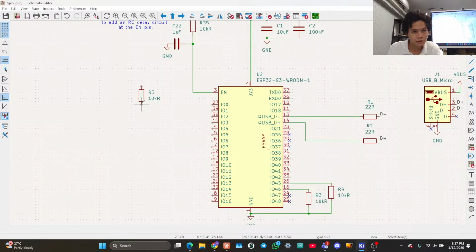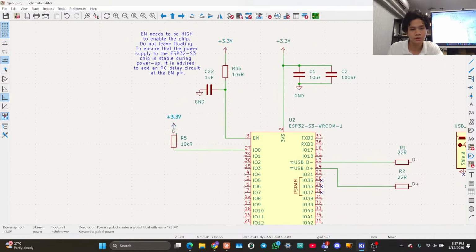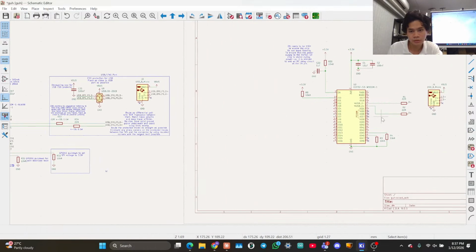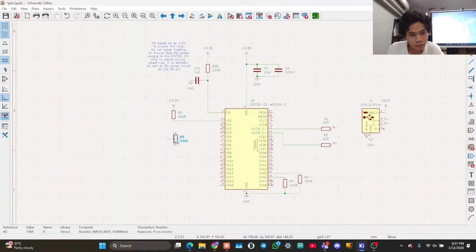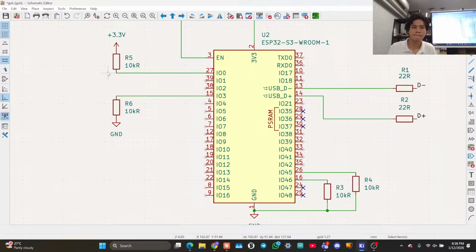Have you explained clock resistance? We haven't. You want to explain? Okay, so the reason why we add a resistor is those are normally pull-up resistors. So you just want the value of that pin to be 3.3 volts or ground, depending on what the resistor is connected to. How does this differ from a normal resistor? We call it a pull-up resistor because it pulls up to the voltage rail. The opposite of it is called a pull-down resistor, which pulls it down towards ground.